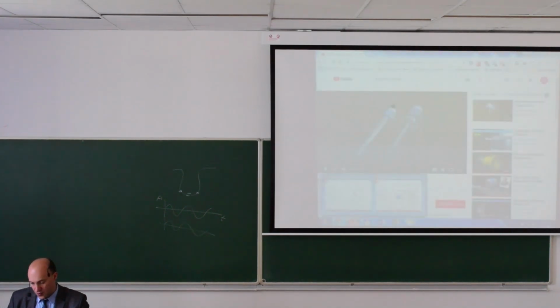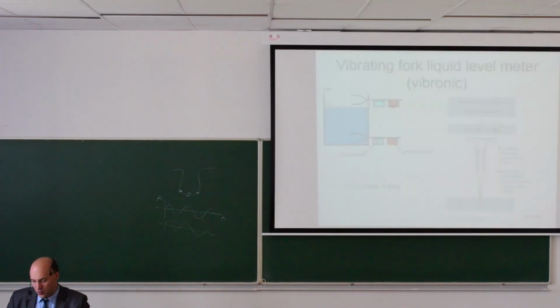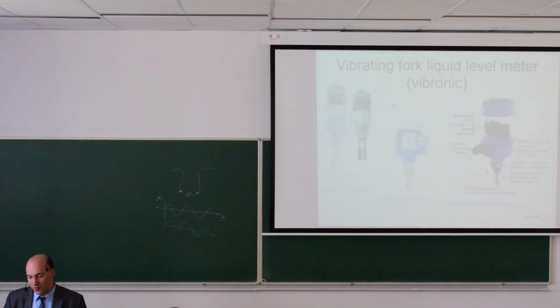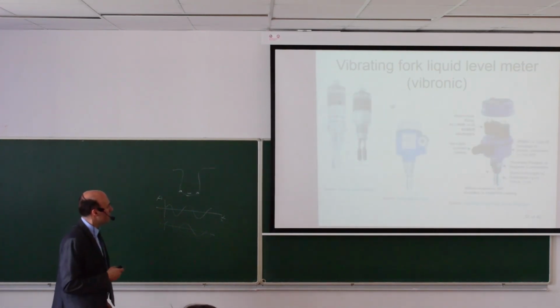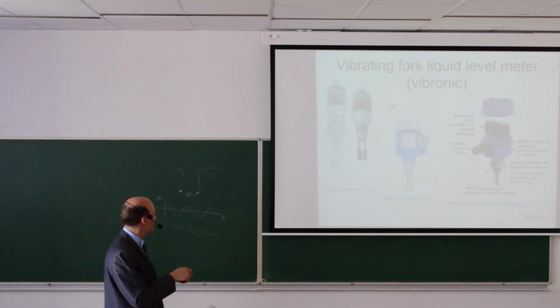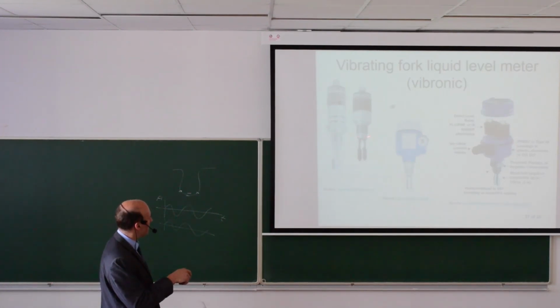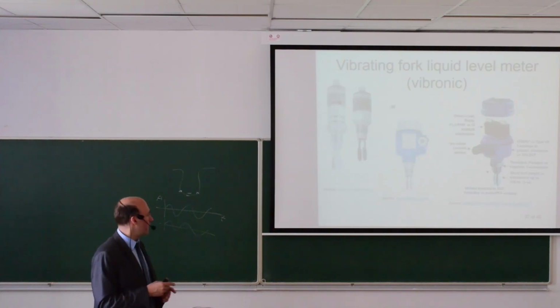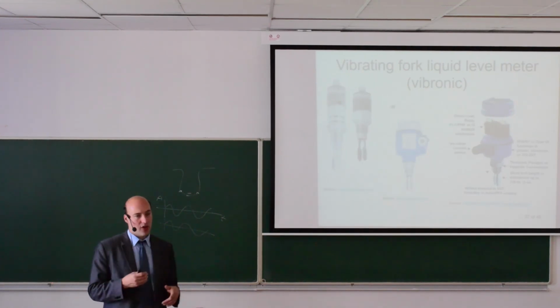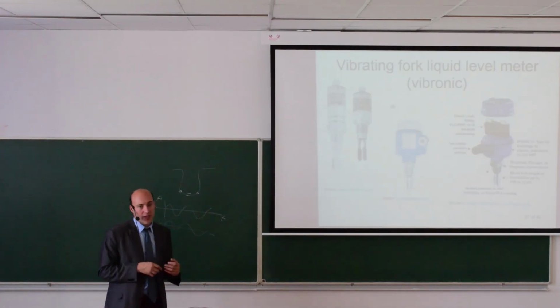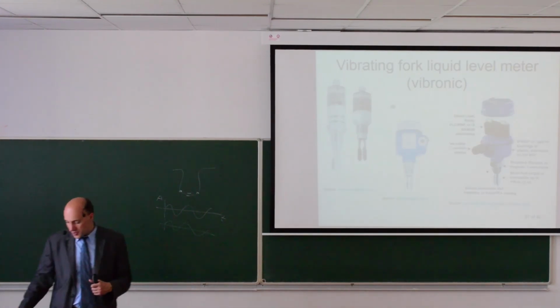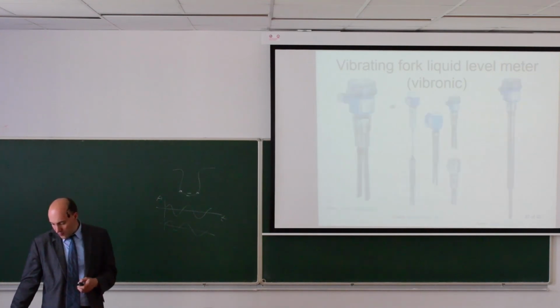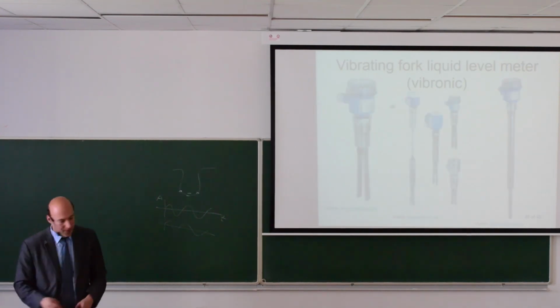Okay, so let's take a look at the properties of this sensor. So as we have seen, it's suitable for liquids and solids. We have seen the principle inside. So this is the tuning fork itself. This is the membrane, and here is the piezoelectric stack. It makes the fork vibrate, and when you submerge it into the liquid or in the solid, you are changing the resonance frequency. So here are a few examples of those sensors.